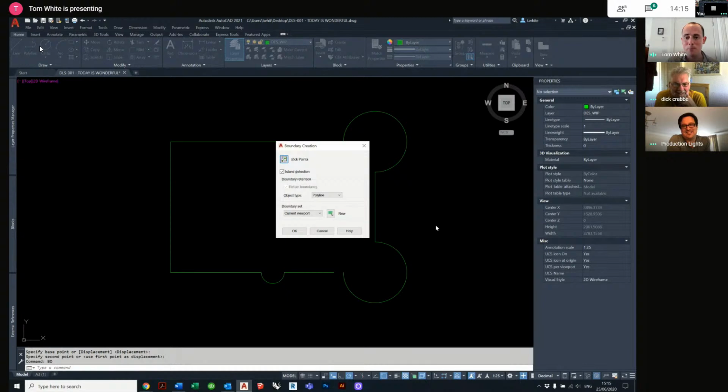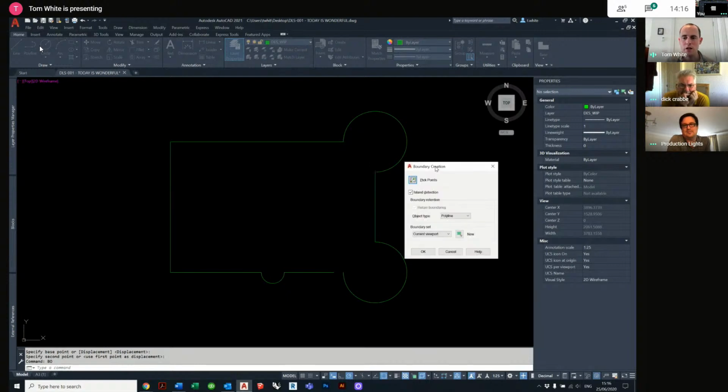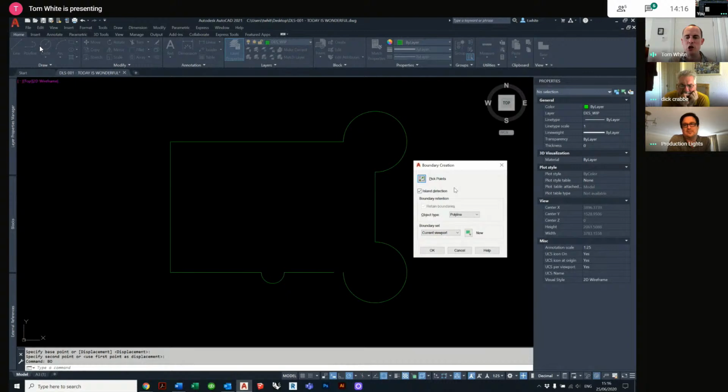The boundary command, in my opinion, and Dom might have a different opinion, but I believe within AutoCAD it's got to be the same thought process as hatch, because it does the same thing. So I've used the boundary command. A dialog box has come up. It's asking me to pick an internal point of the element it wants a boundary of. A boundary, in our minds, we could think of as a site boundary, a festival with a site boundary, where you want to determine the whole boundary of the Harris fencing or something. So this might be a circumstance for that.